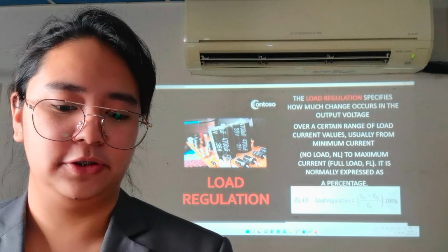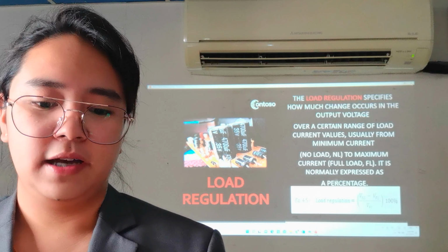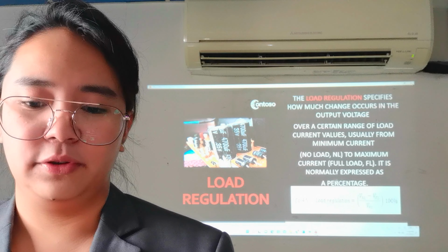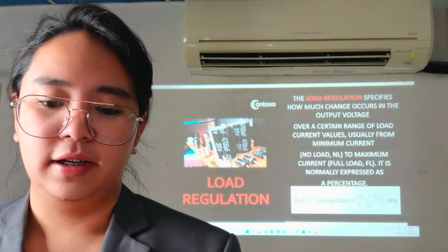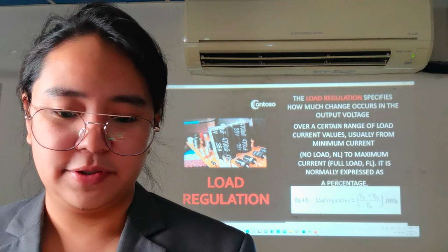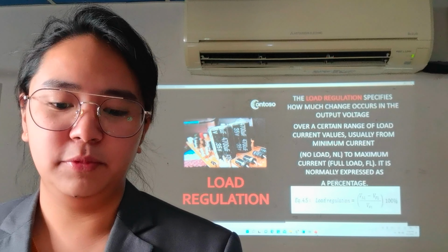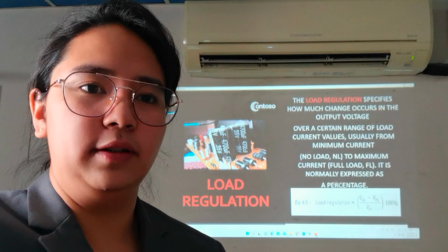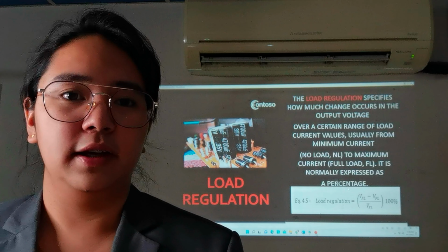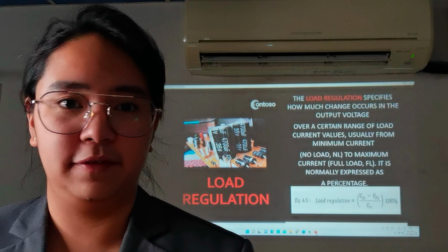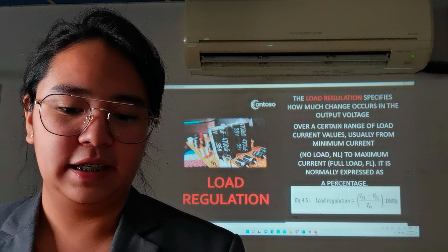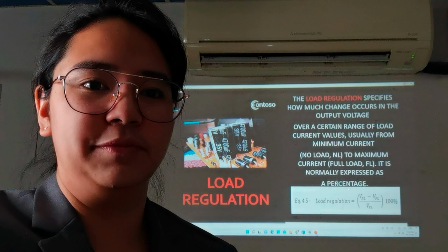Load regulation specifies how much change occurs in the output voltage over a certain range of load current values, usually from a minimum current, no load, NL, to maximum current, full load, FL. It is normally expressed as a percentage.